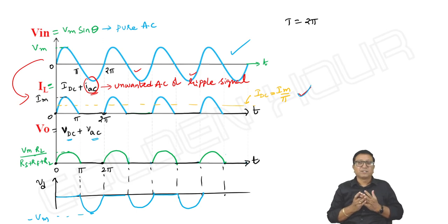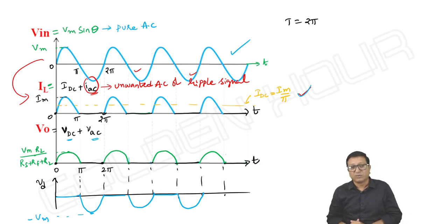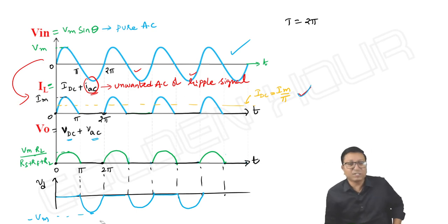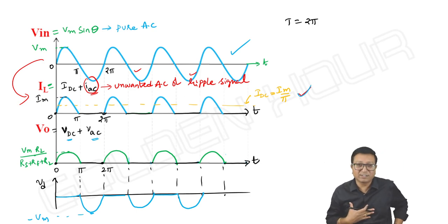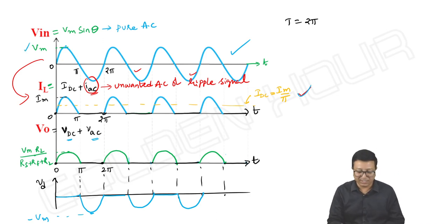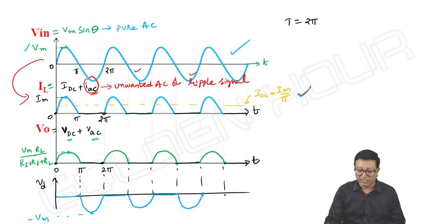And how much? Right here we are calculating what peak voltage the diode is handling. Why are we calculating it? Calculating this means the diode is ready to hold the signal. It doesn't mean that any amount of signal can be given. If the amplitude Vm of the secondary voltage is more, the peak amplitude is automatically more, so the IL peak amplitude will be more and the output voltage peak amplitude will also be more, so that IDC will be more.